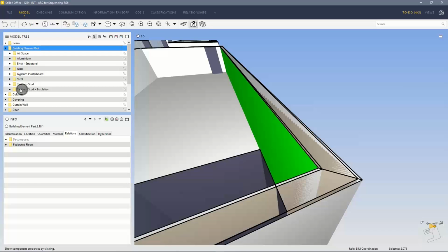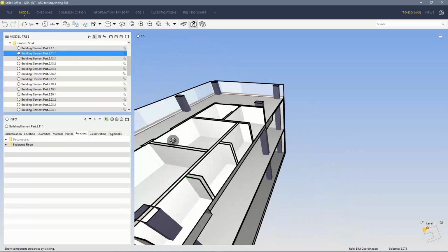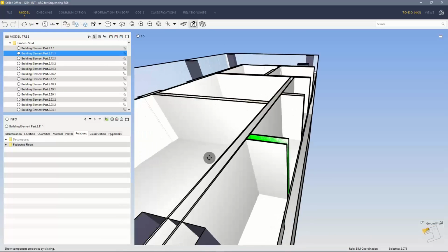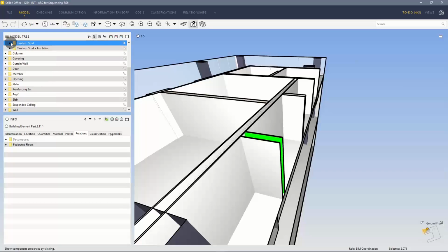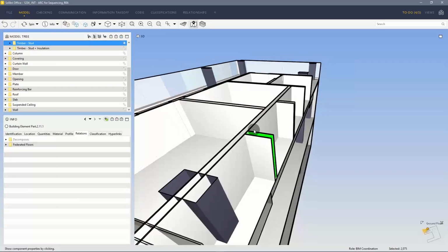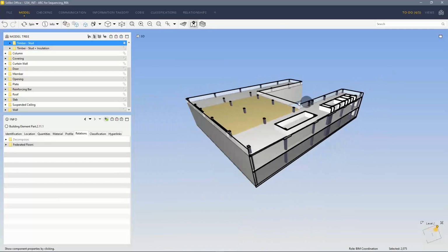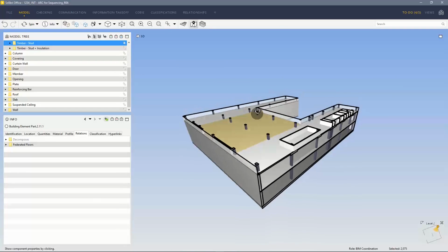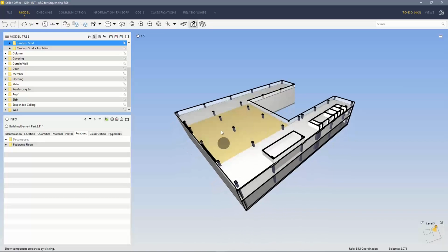So, for instance, these timber studs should be right here, and they can be selected individually from the actual boards. So that's the whole purpose of building it up and exporting it by splitting the elements into individual parts and keeping the hierarchy of the different system tools as they come out of Archicad. That'll help quite a lot when you're trying to do a sequencing out of this model.